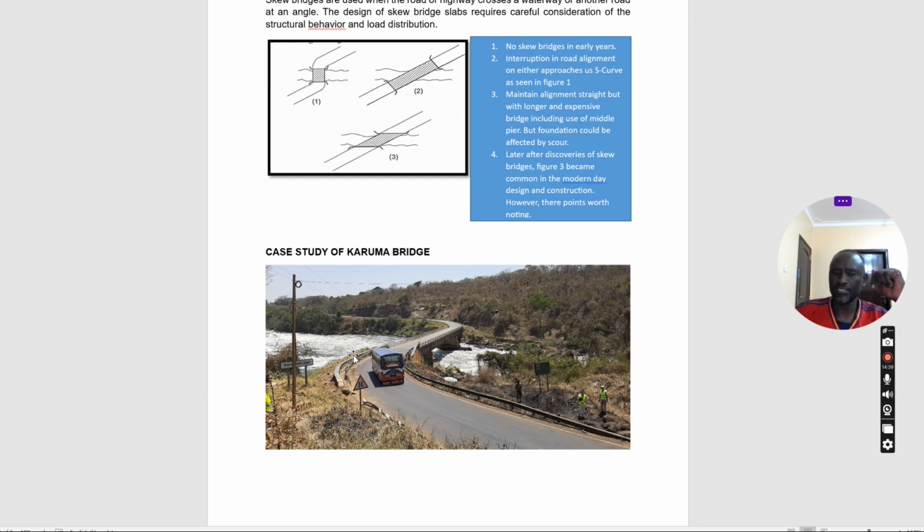So definitely that means that even in design, whoever is trying to model needs to understand the properties of the bearing. There are different bearings you have. You may find that there are special bearings that you need. You may not have elastomeric bearing in either of these areas, or if you have to use elastomeric bearing, there could be certain parameters that need to be adopted. You may not have them uniform because of the response to these abnormal forces. So it is very important.